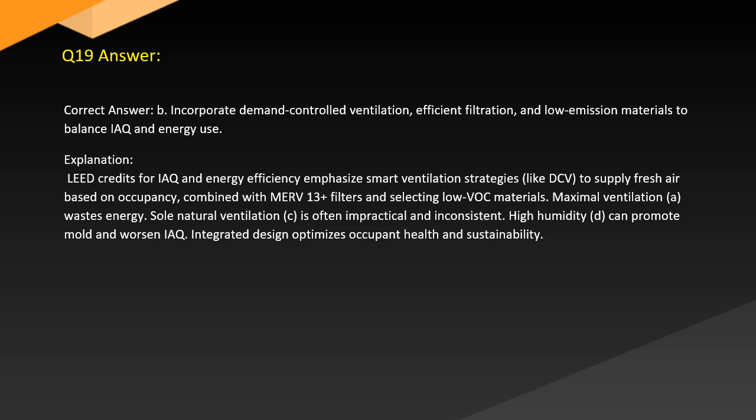Explanation. LEED credits for IAQ and energy efficiency emphasize smart ventilation strategies like DCV to supply fresh air based on occupancy, combined with MERV 13 plus filters and selecting low-VOC materials. Maximal ventilation, A, wastes energy. Sole natural ventilation, C, is impractical and inconsistent. High humidity, D, can promote mold and worsen IAQ. Integrated design optimizes occupant health and sustainability.